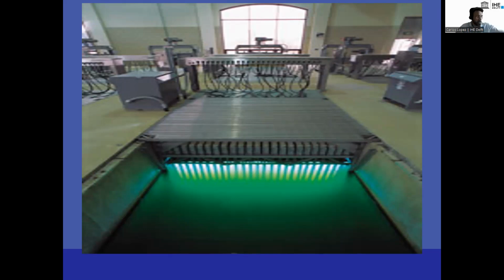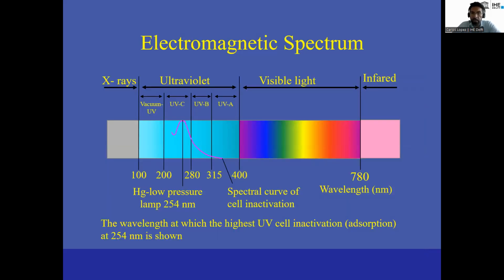In order to make it a bit more economic, filtration, like sand filtration, can be a bit more economic than applying some membranes, mostly to clean and get rid of some suspended material that may interfere with transmission of the UV light through the water, achieving a higher disinfection level. How does it work?